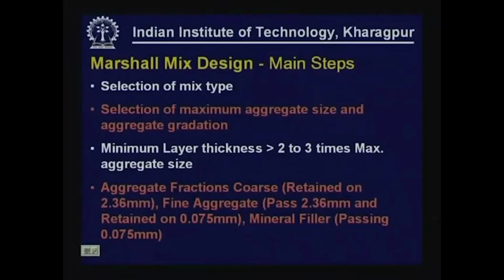So, according to the requirement, we have to select what is the type of mix that we are going to select, and having done that, we will select what is the maximum aggregate size and select an appropriate aggregate gradation. Maximum aggregate size, as we indicated earlier, will be selected on the basis of the thickness of the layer that is going to be provided,